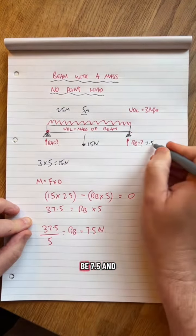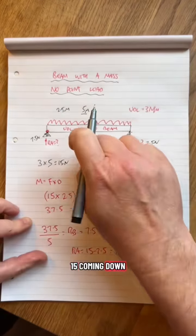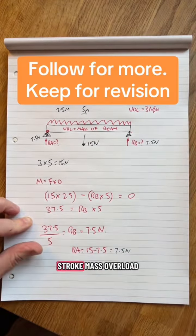Which makes sense, with the 15 smack in the middle. So that's going to be 7.5. And obviously RA is going to be 15 take away 7.5, which also gives me 7.5. What goes up comes down. 15 coming down, 15 coming up. Beam with a UDL, stroke mass. Over and out.